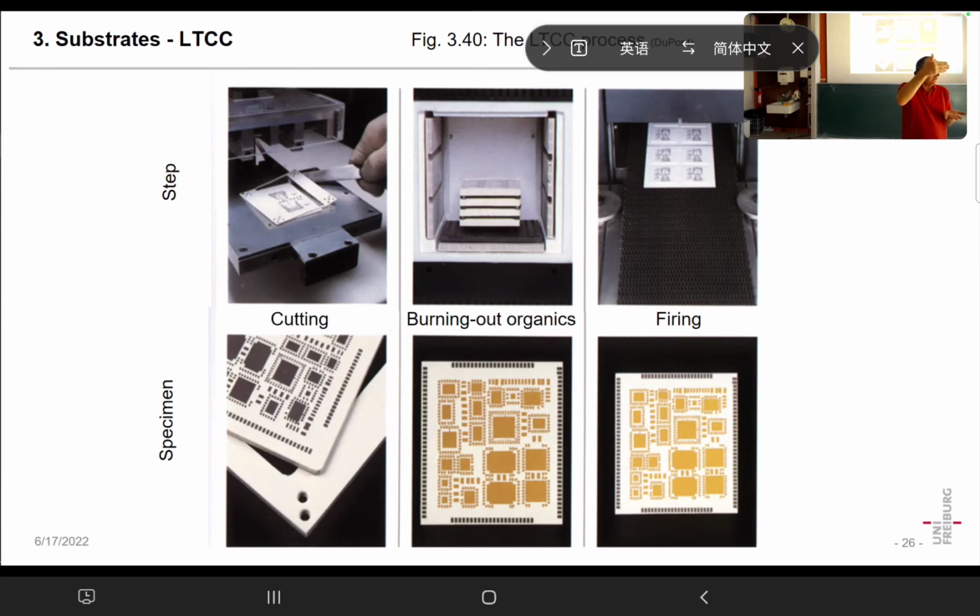Then it looks with a vision system and decides that's the middle of the pad, and then it bonds into the middle of the pad. So for wire bonding nowadays in modern technology, it is not a problem, because we have bonding which finds its bonding site.